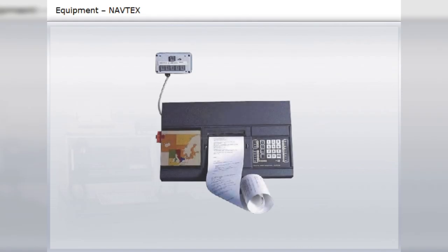Via this Navtex you will receive maritime safety information, MSI, as nautical and meteorological warnings. Certain groups of coast stations transmit in MF frequency 518 kHz on a time-sharing basis. Coast stations may use 490 kHz for transmissions in national languages. 4209.5 kHz is also used for Navtex transmissions using telex onboard ships.